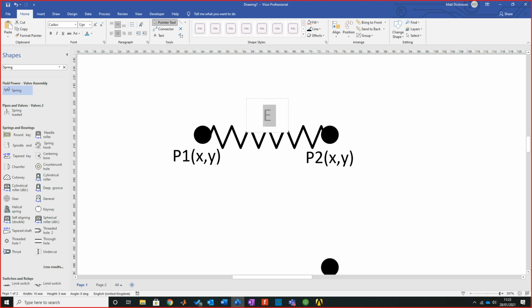So when you actually look at FEA packages, be it Abaqus, which is the biggest one that's attached to CATIA, be it ANSYS, which is very popular and industry based, or be it COMSOL, which is very popular nuclear based or in academia, they all three do not represent the behaviors of elements with E. They actually represent it with K.